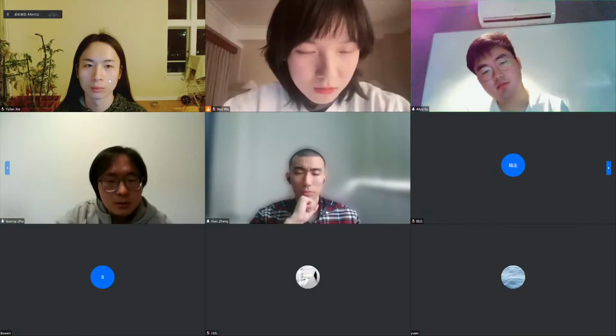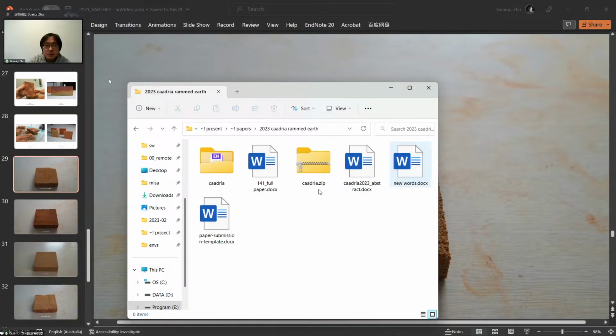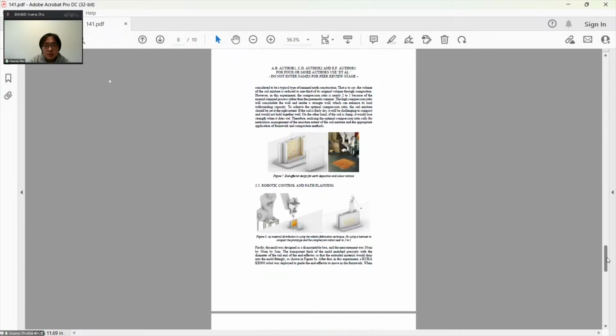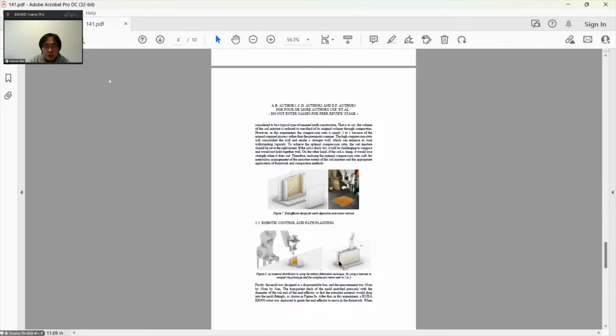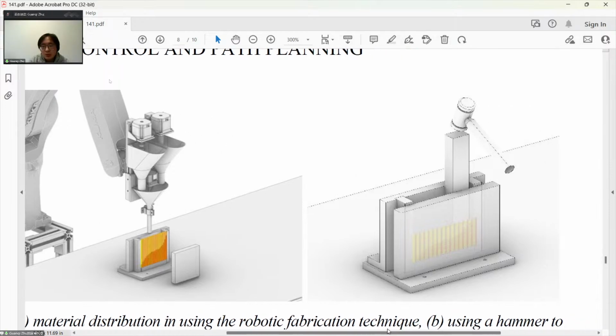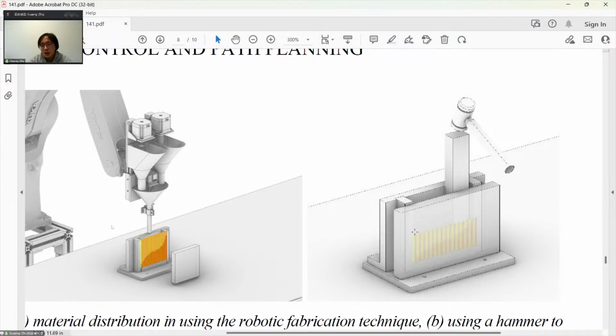Okay, thank you. And for the coloring gradient here, the strength, right? In this paper, I'm trying to discuss the compression ratio, if my memory is correct. After you printed the earth, you still need some high strength to compress it together. It is recommended that the compression ratio is 3:1, but if you only finish by hand, the compression ratio is only 2:1. Maybe my strength is not enough, but if you use a mechanical method to compress it really dense, it will absolutely improve the structural performance.